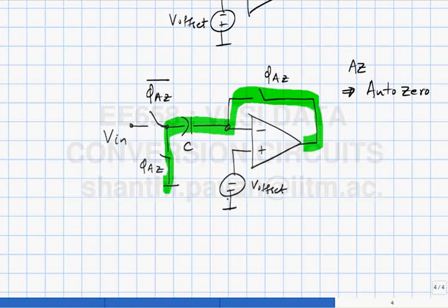So there are people who do this, but this involves, as you can see, a lot of time first of all, as well as a lot of digital circuitry, right? So you need counters and all this other stuff. But this is also done in practice. Okay. When it becomes difficult or very expensive in power terms to have a preamp, because please note that the preamp draws static power. It's always carrying a current 2I, whereas the latch only draws power during switching. So if the frequency of this operation is very, very low, it doesn't make sense to go on burning current. Okay, some strategy like that probably makes more sense. So I will stop here.